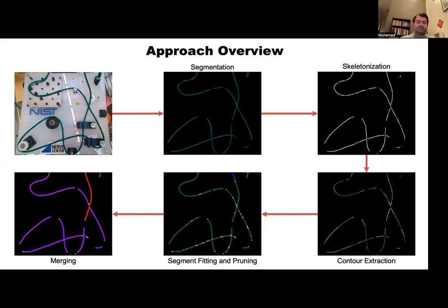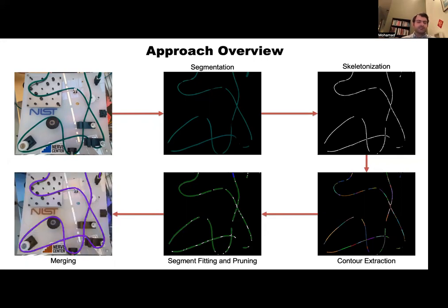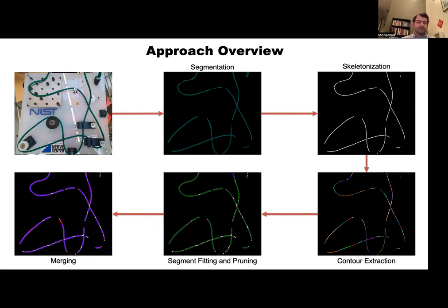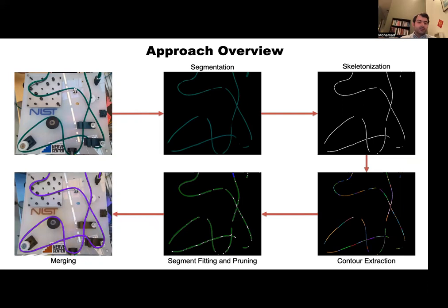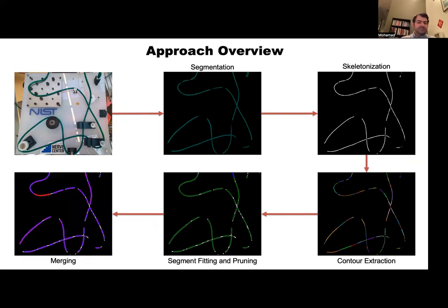Each of these extracted contours is used for fitting a small DLO segment, and then all overlapping segments are removed. Finally, we iteratively find two DLO segments that are the best fits and connect them together using a computed curve. The final output is a single DLO represented by a sequence of short fixed-length cylinders connected to each other using a spherical joint.